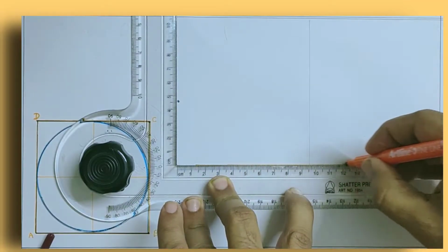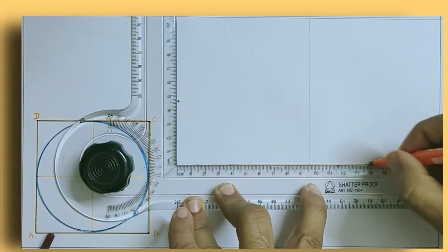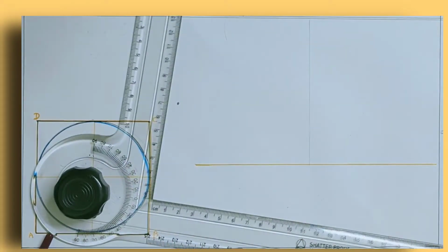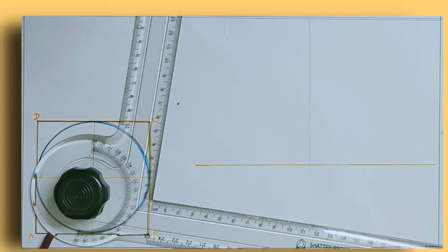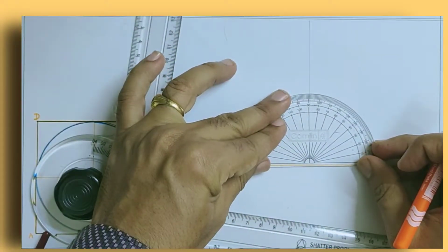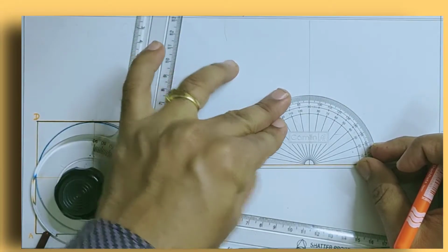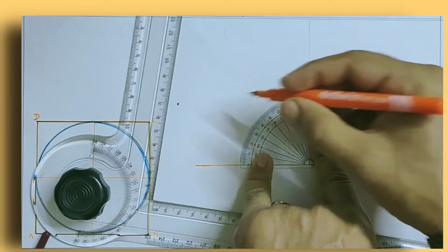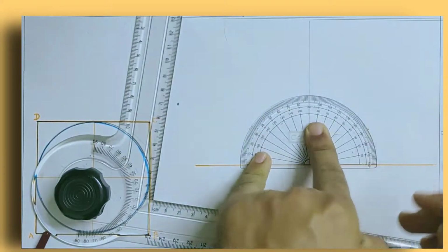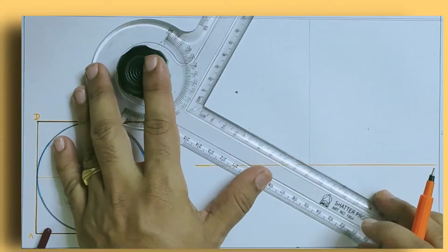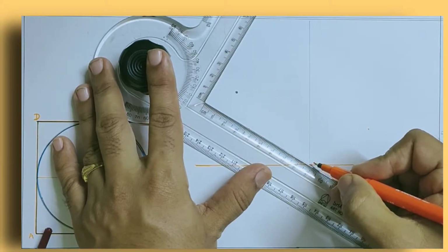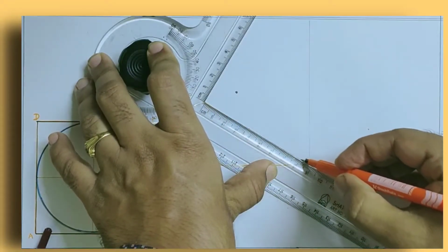So what you can do is you can just draw a reference horizontal line, just a horizontal line as a reference, and then you can draw the 30-degree lines directly. Instead of going for a vertical line, you can just take only 30 degrees. So here just take 30 onto this side. Based on the precision what you're going to use, so will be precise the ellipse. If not, you'll be getting the intersecting arcs or discontinuous arcs.